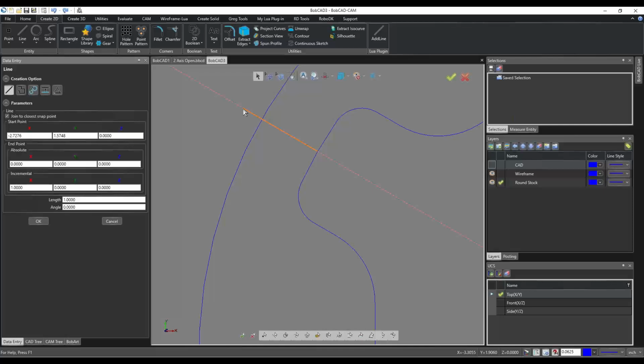If you don't want to use them, you can shut them off down here. At the bottom right of the screen, there's a couple of toggles, and one is called Use Construction Geometry. Just click on it, and that will disable it. There's a couple of other cool little tools down here that maybe I'll go over a little later. But let's go ahead and move it down this construction geometry there, click again to place it down, and then click OK and cancel.